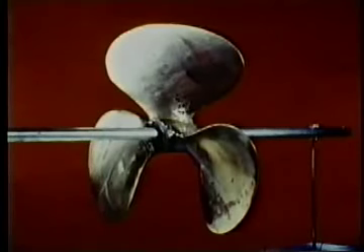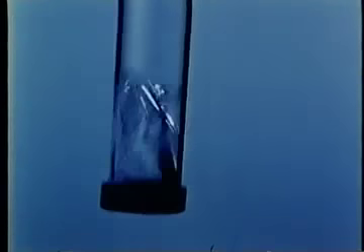Here is cavitation damage on the runner of a large hydraulic turbine which operated under cavitating conditions for an extended period of time. This propeller operated under cavitating conditions for only a few days. Similar damage can be produced on pump parts, such as this impeller of a pump for high-temperature liquid sodium, and in the low-pressure regions of hydraulic structures, such as this large power dam spillway tunnel. There has even been speculation that brain damage can be produced by the collapse of bubbles in the cranial fluid when the skull is accelerated under the action of a sharp blow.